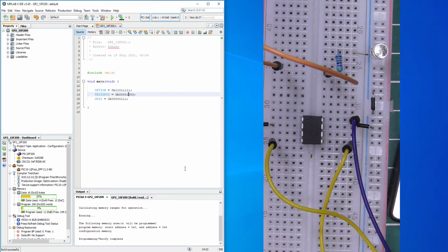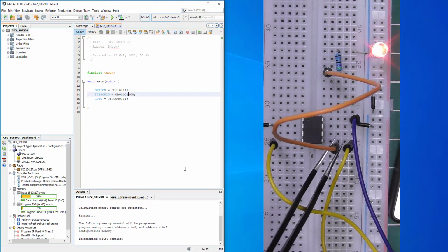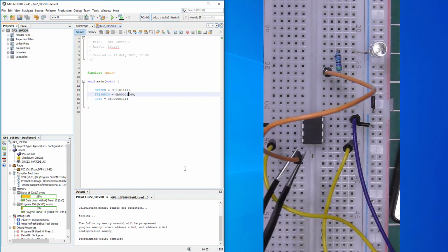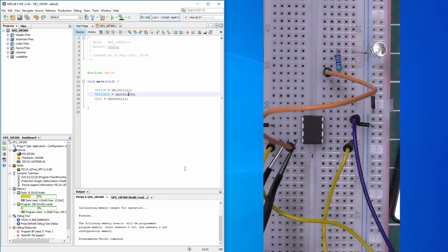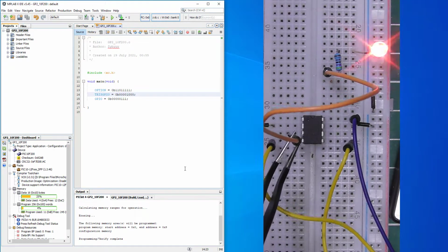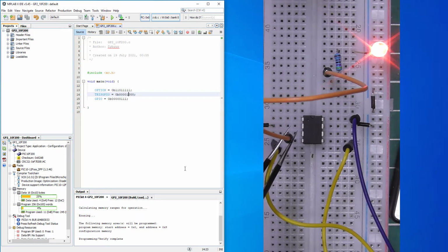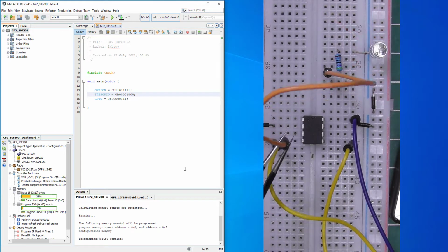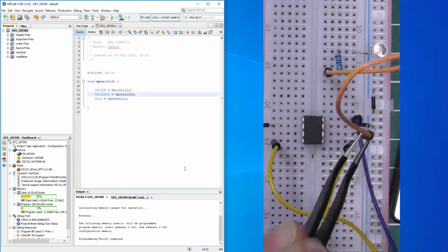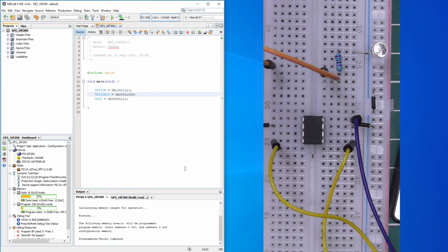and have a look at what is happening now with our PIC microcontroller bits. Okay, 0 is high, 1 is high, 2, there we go, is high. Now we've got access to this bit because the OPTION register switched off the timer function. GP3, we know we can't use because it's input only.